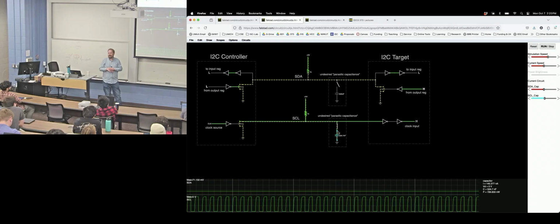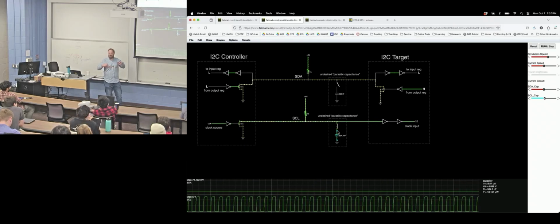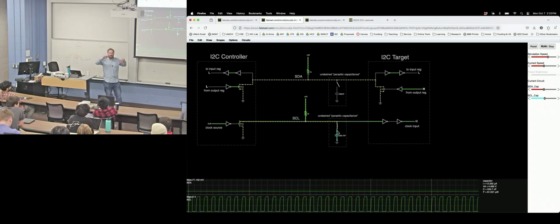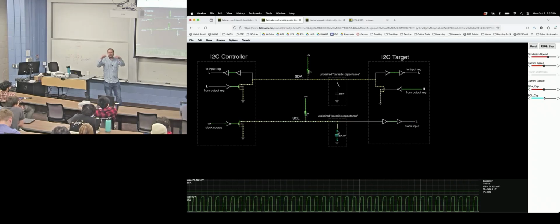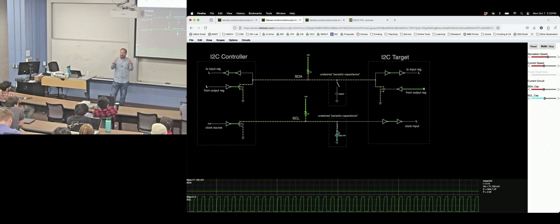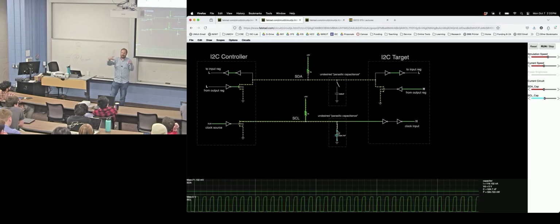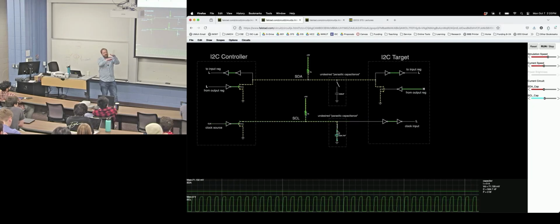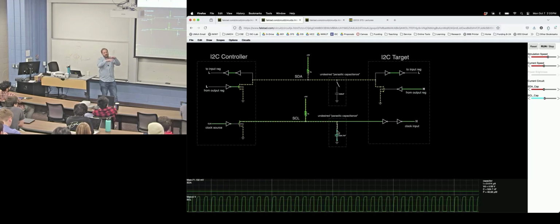What's another mechanism for capacitance? Yeah. Transistors. So like if we expand that idea out a little bit, your pin on your microcontroller and all the transistors that get connected to it will actually have capacitance there on the line. So you might test your device in isolation and you're like, oh, all the square waves are just nice, and you put a load on it, like a GPIO pin, and all of a sudden they start getting smoothed over. Also the geometry, maybe this is what you're saying a little bit, your traces over a ground plane or connected to other things will add some capacitance.